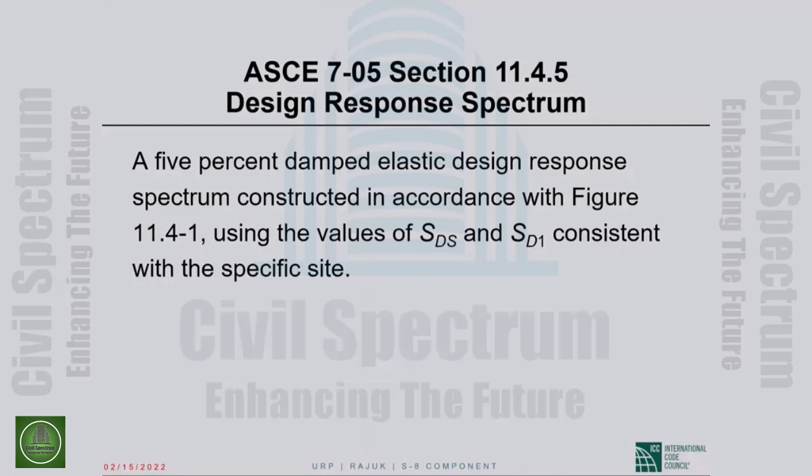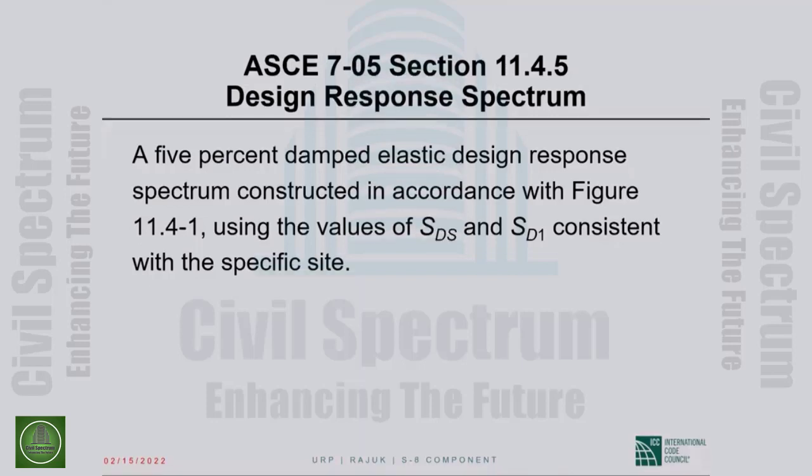Or in your case, you can use the BNBC spectrum or whatever. There can be a site-specific spectrum, but you have to have a spectrum. If you want to do modal response spectrum analysis, the earthquake input, what the earthquake is feeding into the structure, will come from the spectrum.